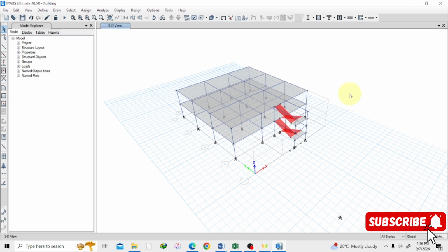So when you want a very good accuracy, you try to make the divisions quite smaller, but you also have to put in mind that when it becomes too small, the analysis of the various sections become too many for the software. So when it's designing the slab or running the analysis, everything becomes slow, it takes time. And we also make sure not to divide them into bigger sections, because it creates inaccuracies. So this is what we have to take note. I know right now you might not be really understanding what I'm talking about, but at the end of today's video, you are going to get it and you're also going to enjoy.